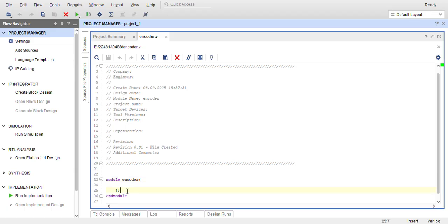So first we have to do the code here. For that I have to take the input. So what is our input? For that we simply write the input keyword. So what are our inputs? There are only 8 inputs. So by using one variable you define the 8 pins. How? By using the vector format, 7 down to 0. Those are the 8 pins, those are the inputs.